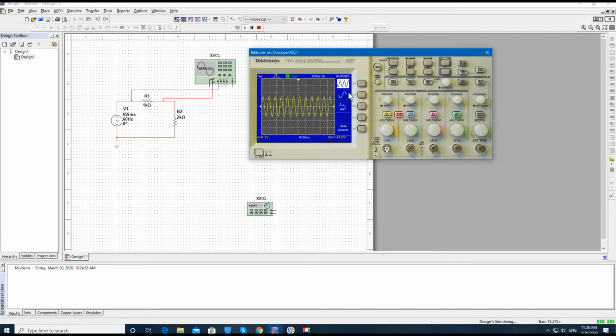Then you can use a single sequence and go to measure, click measure, and then you can adjust what voltage you want to display. For example, click on that one, click on the top one, and then click here. You can measure minimum, maximum, rise time, fall time, and anything that you want. For example, here I put the frequency and then hit measure again. It will show you the frequency of the signal and the amplitude, whatever you want.